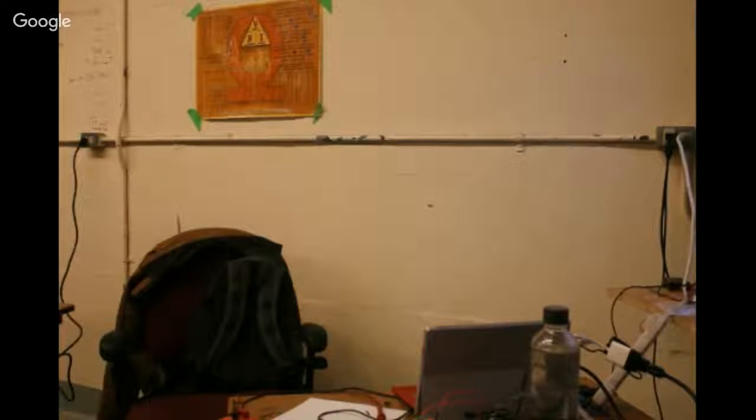I might also point out that when this is actually connected, you want to have the plastic cut pretty much exactly close to the end, because otherwise, when it pulls the wires in across the channel, if your solder and plastic are right up against it, you won't have room for it. So shortening those wires down, that's what Derek was just saying. The parts that are going to be attached to the strip should be much shorter.